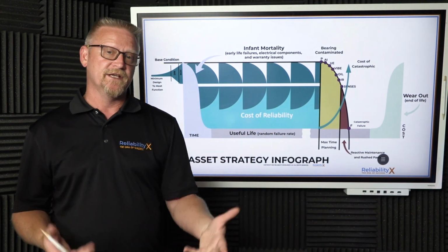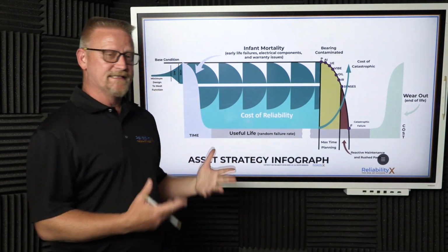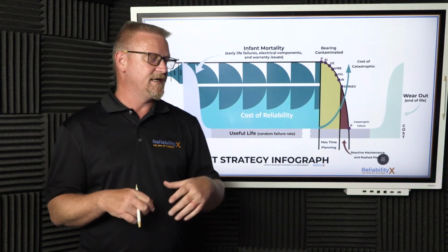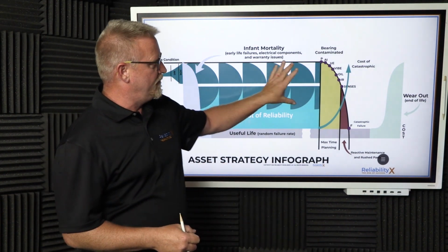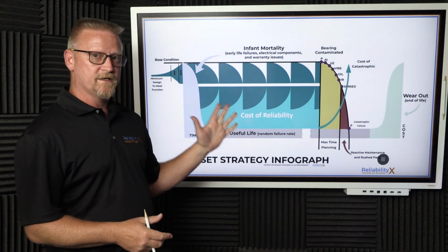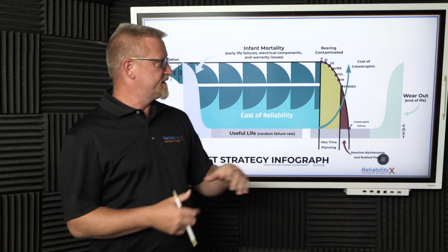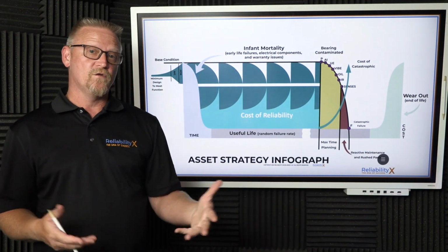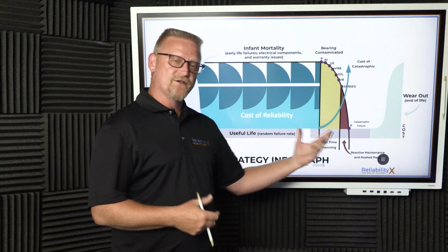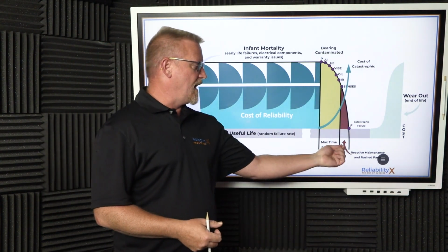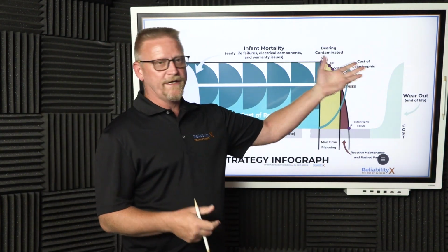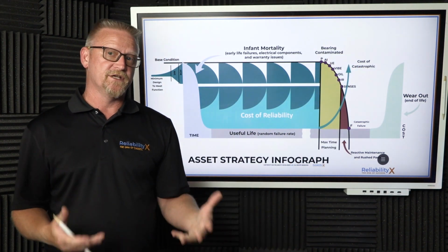And so, as you can see, we utilize techniques like design for reliability and RCM and FMEA to get a much more robust maintenance strategy with lower costs and lower interventions, or at least less frequent interventions. We utilize predictive technologies to buy us a window of time so we're not living just in a reactive domain, and allow us to avoid the catastrophic event and the additional cost.